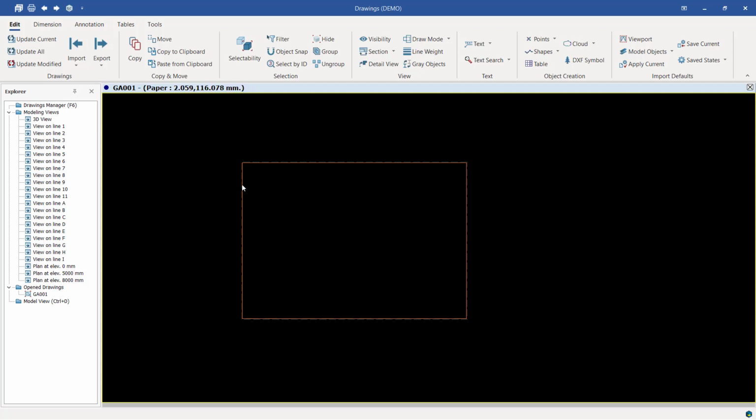Once the changes are saved, I'll be prompted with a huge borderline. This is just a boundary that frames where we will be placing our drawings, defining a boundary where all the drawings that you generate as a GA will be placed automatically. Once we have this borderline, this is the place where we'll be placing our drawings that we have defined as a general arrangement drawing.